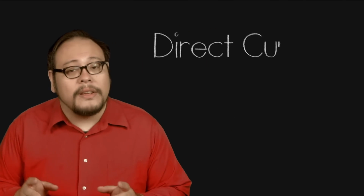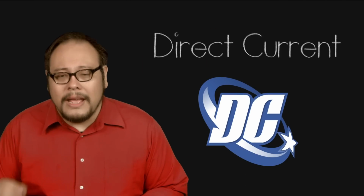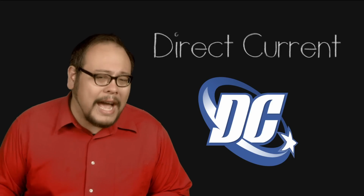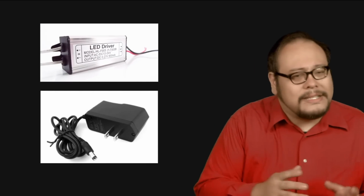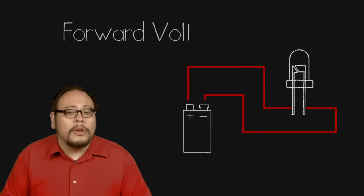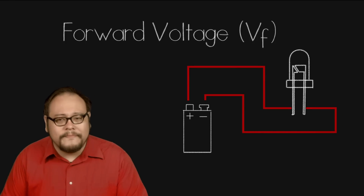First thing, when we're dealing with LEDs, we're dealing with direct current, not alternating current. DC is the power you get from batteries. And if we're tapping into AC power, we'll need to convert that to DC using an LED driver, but we're getting ahead of ourselves. To get an LED to light up, we need to apply a certain amount of DC voltage called the forward voltage for forward bias.